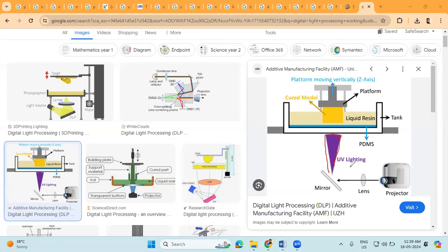Okay, so the vat photopolymerization process relies on the integration of multiple advanced scanning systems, each with its unique functionalities. These systems encompass galvanometer, flying liquid, flying optics, DLP, etc. DLP entails an array of mirrors and is a prevalent technology in modern projectors. In this DLP, you can see a projector casts light over the entire layer to cure it all at once.